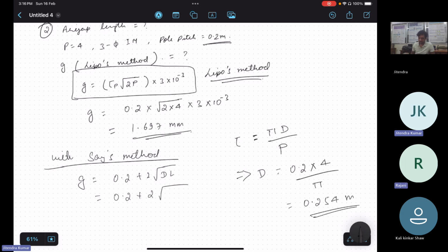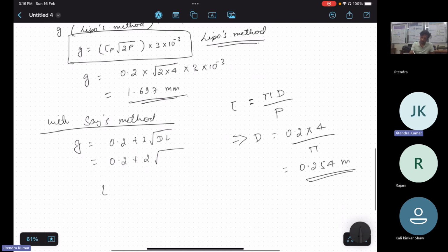Okay, thanks. L by D ratio is 0.2 for induction machines, sometimes. That is too low, I guess. Are you sure 0.2 is there? Actually, for DC machines, we used to take 0.6 to 1.2. For induction machines, better we go for 0.2, 0.4. We cannot say exactly, only approximately.